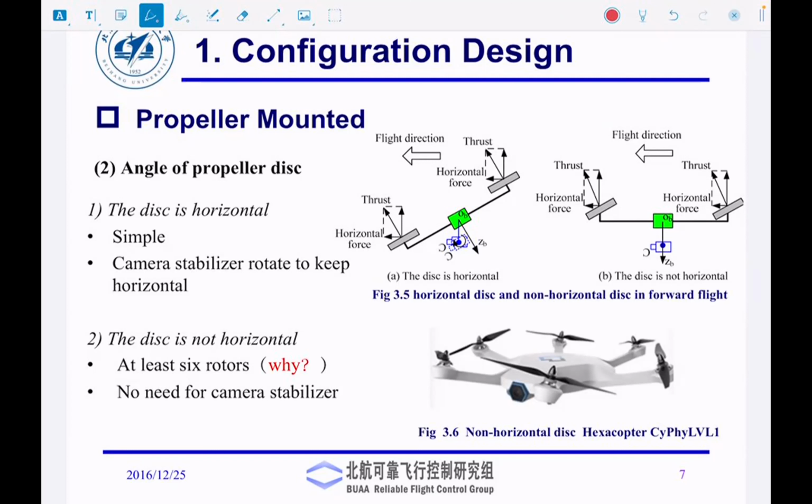Depending upon the designs that you use, nowadays the drones are used for, say, photogrammetry. I don't know if you know what photogrammetry is. Basically, the drone will fly, take pictures, and then you get those pictures, stitch them together, and give you something like a Google view. And it will do it so nicely that you can select the points, and it will tell you the distances. So basically, you will fly multiple drones, and those drones will stream the images. Those images will get stitched, and then the person who is sitting at the ground station can click a point, click a second point, and find out the distance between those two points.